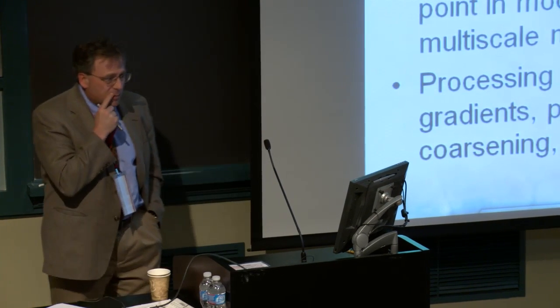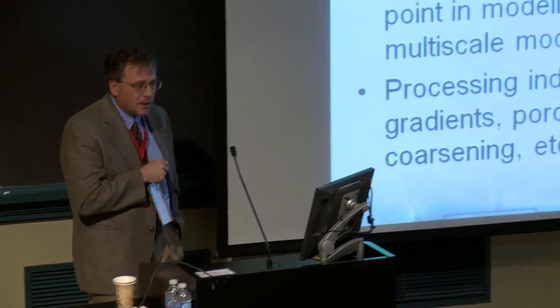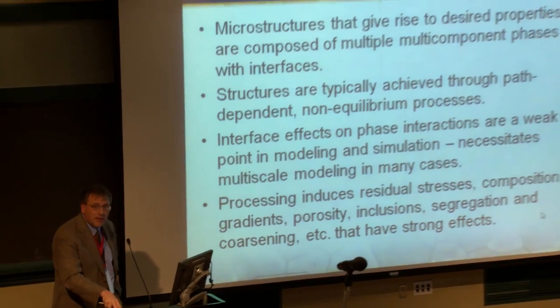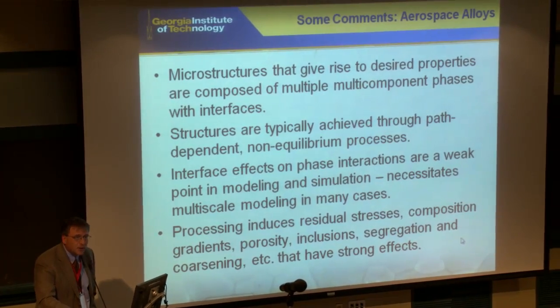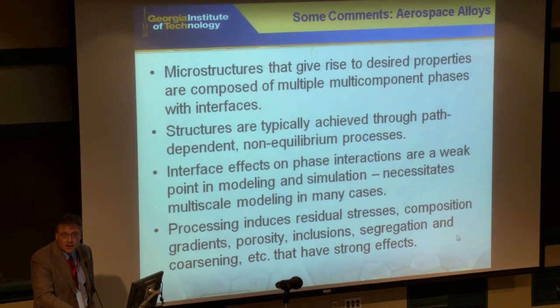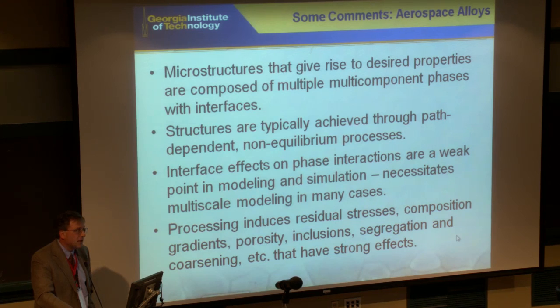Some comments on aerospace alloys that I think are relevant to the discussion. It's important in discovery to look for stable phases. It's important in development to understand phase interactions and metastable, non-equilibrium phases, and how you engineer those, understand the kinetics. The thermodynamics is still extremely important.